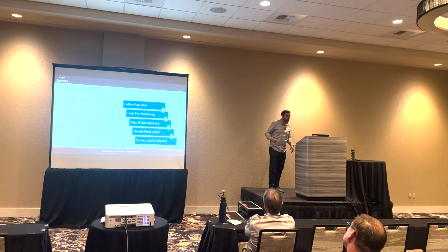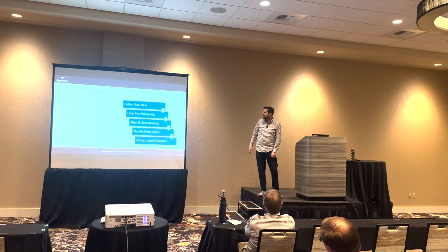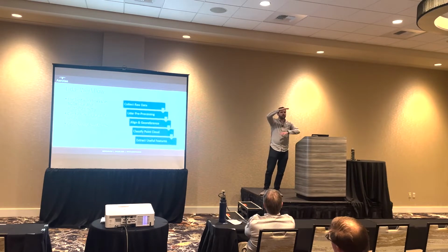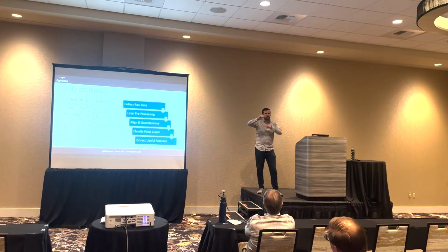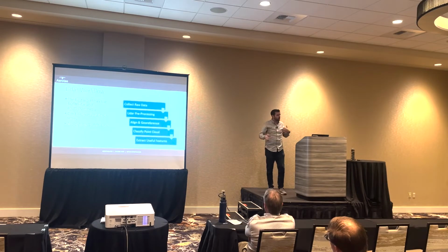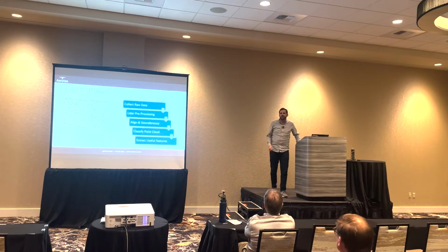That's one of those pitfalls that I should point out we really, really don't like. When you don't have a clearly defined workflow, you might start classifying your point cloud, run some of those automatic routines, and then georeference it after the fact and realize two different swaths were off by a foot. The one on top was all classified as non-ground and the one on bottom was ground, when they should have been aligned and been the same thing. So we really like having these as very discrete steps. In fact, in our data tracking system, the project can only be in one step before it gets completed and moved on to the next step.